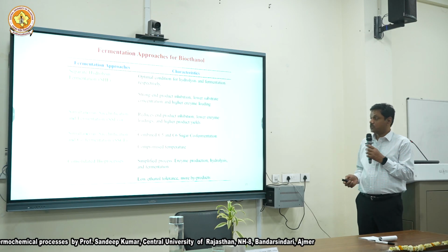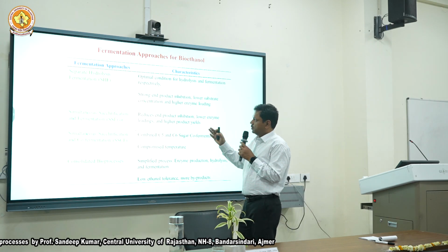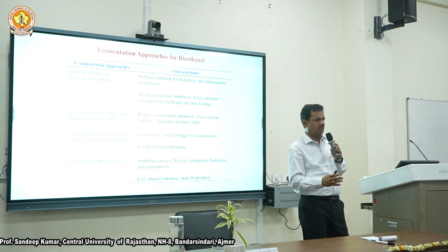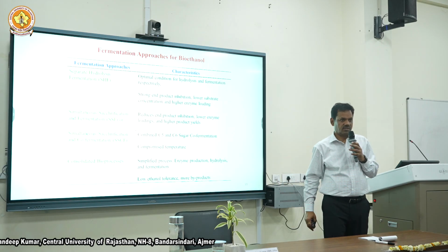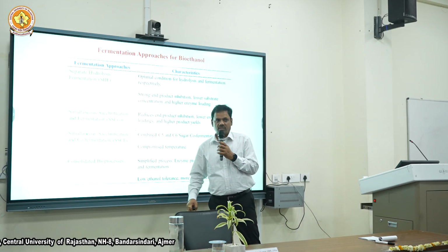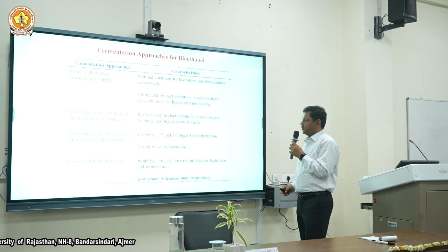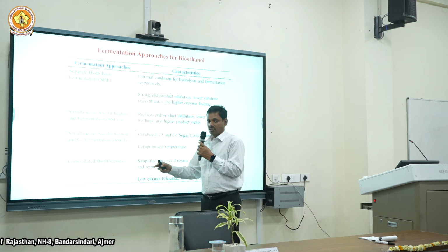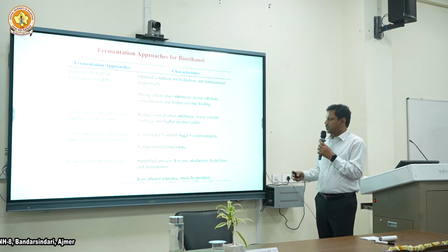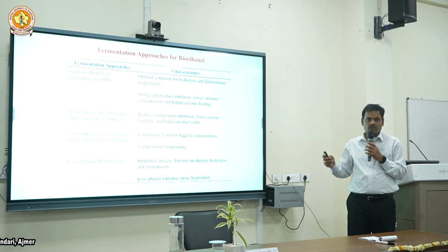There are different approaches for fermentation, especially for ethanol. Separate hydrolysis and fermentation: we have enzymatic hydrolysis and then fermentation. You can have simultaneous saccharification and fermentation in one step. Okay? You can have simultaneous saccharification and co-fermentation, where 5-carbon and 6-carbon sugars go together. Or consolidated bioprocessing, one chamber where you do everything. So these are the different options you have.